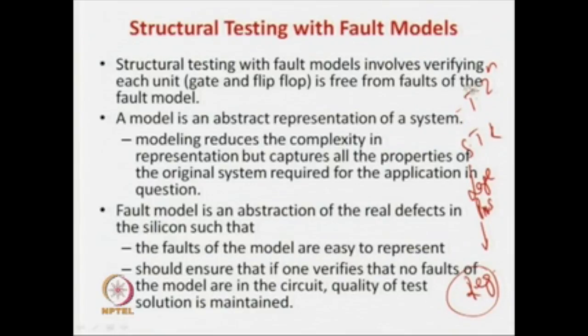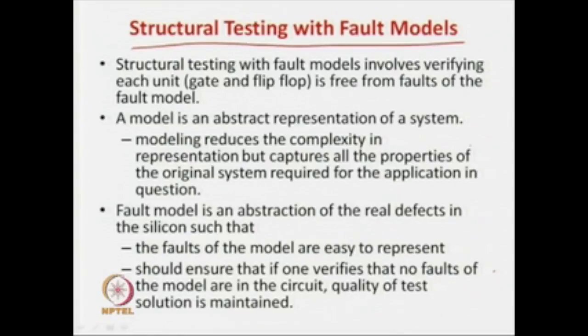So now what do we have to solve? We have to see how we can reduce the large number of registers and also 2:1 multiplexers in structural testing. Again, what came as the solution is structural testing with fault models. Now, again, as we saw in the last example, we have structural testing with a gate as a unit, or a full adder, so what do you verify?